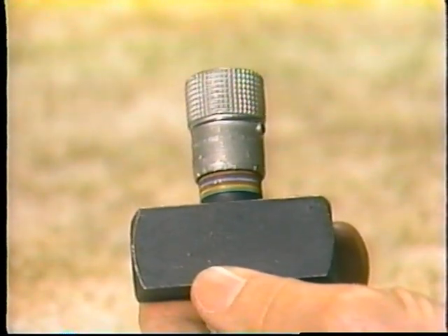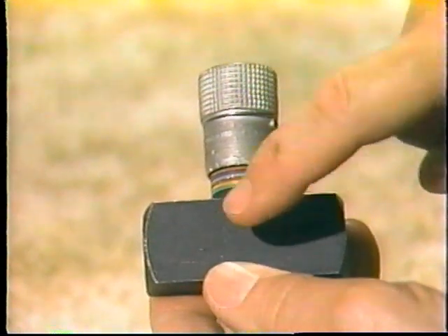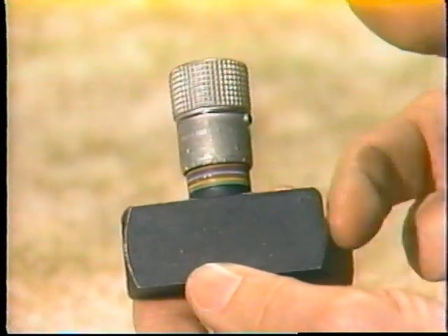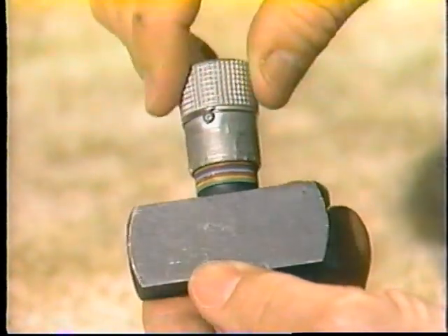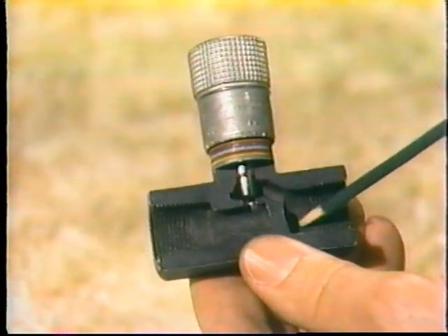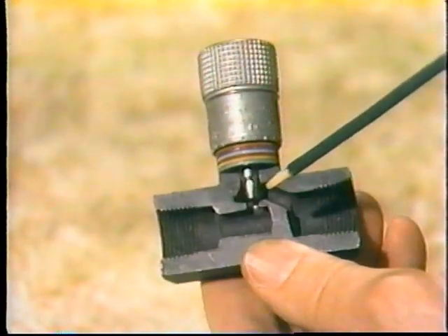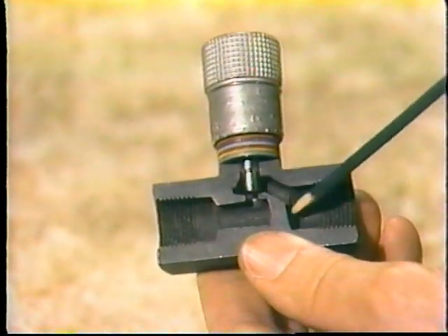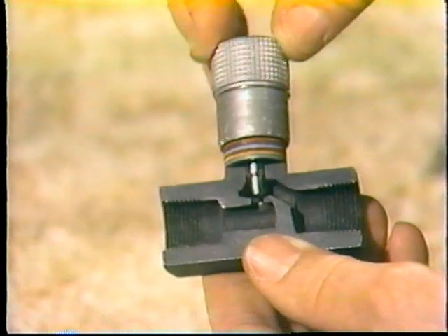And if we had the regulator and the flow control valve set up in a circuit for a certain speed, and then we increased the load, the speed would decrease. And if the load increased enough, it could cause the actuator to stop. Now let's look at that needle valve again. It consists of this valve body with both inlet and outlet ports. Adjustments are made with this adjustment knob. Here's a cross-sectional view. The inlet and outlet ports are connected by this internal passage here that has been formed into the valve body. You can see that the adjustment screw is threaded.